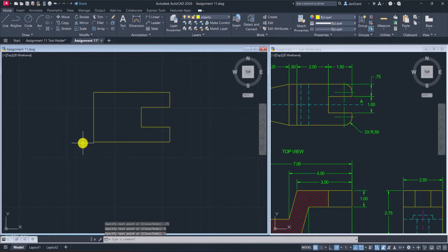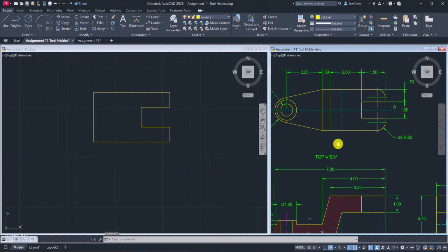Now you know from tracking, which I love, and I didn't do that here, that you didn't have to type in 4. You could rest your pointer up here and track to the next line. We've been learning tools as we go, right? So it's your choice. Here we can offset, right? We have an offset of 0.5 to the right, and we'll hold off on these hidden lines until we get the main outline. So we'll offset 0.5 to the right and 2.25 to the left.